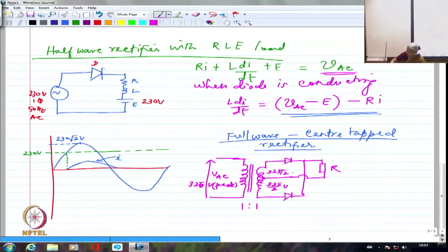Right? Whenever there is a positive half cycle, I am going to have plus here and minus here, because of which I will have again plus here, minus here. And if I am taking half the tapping, I should have the minus point here for the upper half and again plus point here for the lower half. Right? That's how it will be, because it is series connected, series addition. Like when we talked about auto transformer, we used to say series addition and series subtraction. This is series addition, so we are going to have plus minus like this.